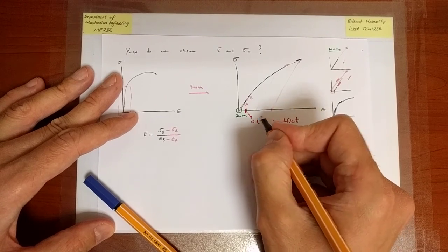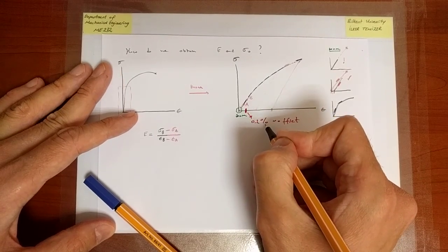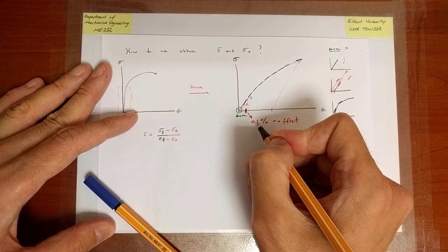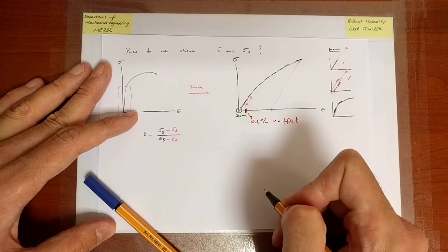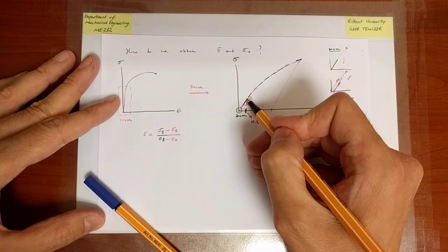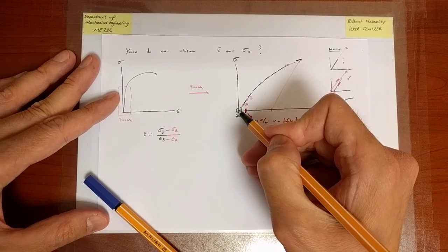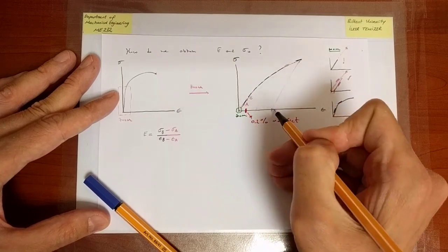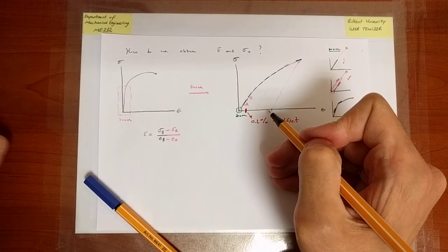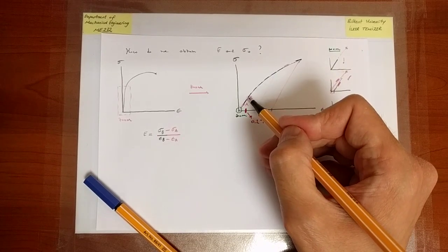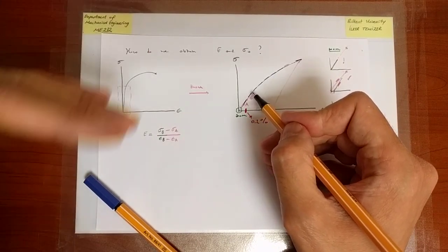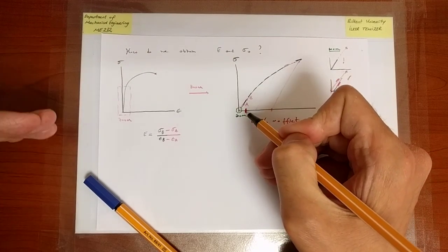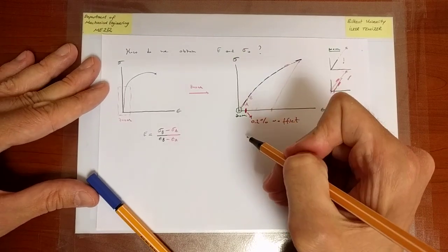I'm writing the amount of strain offset as a percentage. In reality, the strain itself would be 0.002, which is the same as 0.2%. So what people have said is, if I'm in the elastic region, when I unload, I would get zero strain. If I'm significantly into the plastic region, if I unload, I would get a significant amount of plasticity. So to quantify appreciable incursion into the plastic zone, or appreciable deviation in this slope, I'm going to impose some small amount of plasticity.